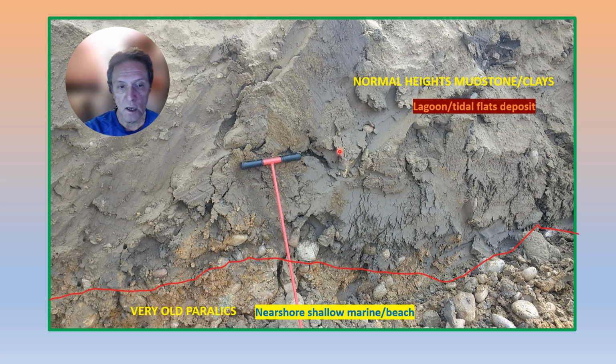So this is that thick clay that's sitting on top of what we call the Linda Vista formation, which are nearshore shallow marine and beach sandstones and conglomerates. Okay, so it's important for the engineering geologist to investigate this, to be aware of it, to bring it to the attention of the design engineers and work with them in coming up with mitigation solutions for any particular structure to be built on top of it.